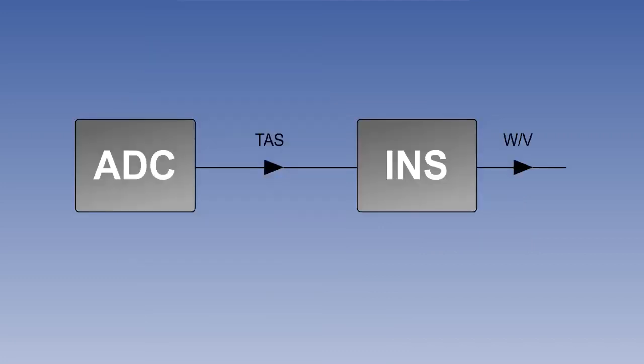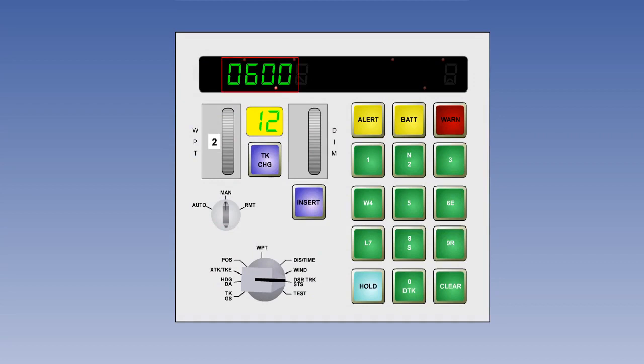However, any aircraft which has an avionics suite sophisticated enough to include an INS will also include an air data computer which will provide the TAS to the INS. DSR TRK STS stands for Desired Track and System Status. The desired track is the initial great circle true track between the waypoints selected in the From To LED display, and is shown to the nearest 1/10 of a degree.